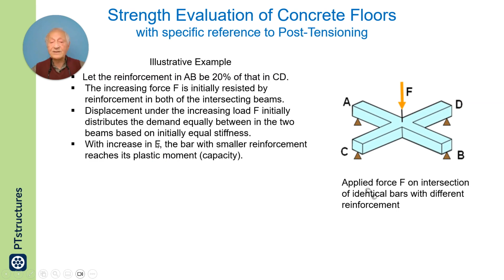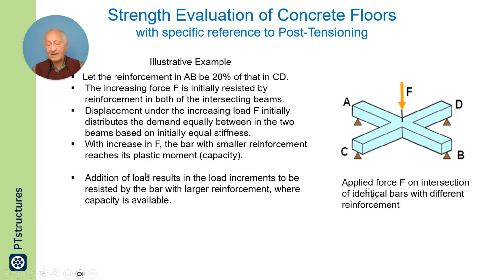With increase in force F, the bar with smaller reinforcement reaches its plastic moment capacity. Addition of load results in the load increments to be resisted by the bar with larger reinforcement, where capacity is available. This is the concept.